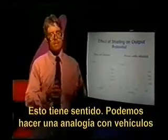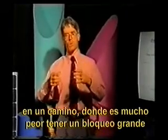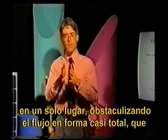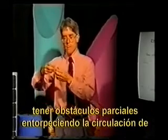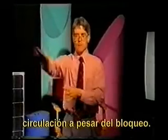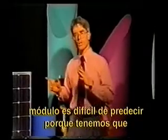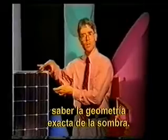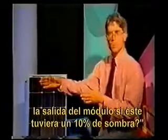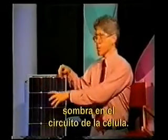This makes sense. We can draw an analogy to perhaps vehicles on a road where it's a lot worse to have a big blockage in just one place, constricting the flow down to almost nothing. Compare that to having damage or blockage along the road, but maybe confined to only one lane of a 4-lane road. There is blockage, but there's much more flow going by. So you can see that the effect of shading on a module is hard to predict because we have to know the exact geometry of the shading. You can't simply say, what would be the effect on module output if I had 10% of my module shaded? We have to know exactly how is that shading spread over the cell circuit.